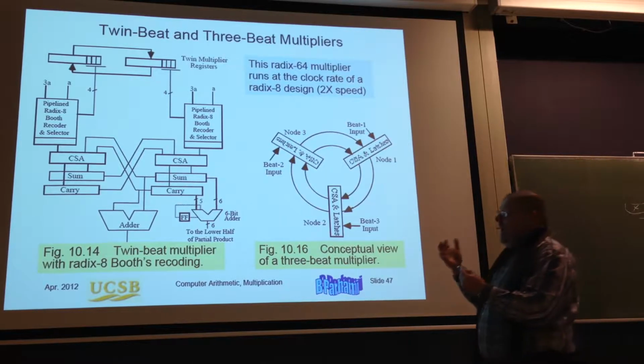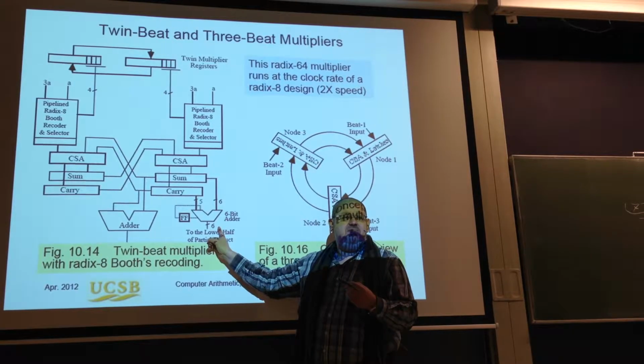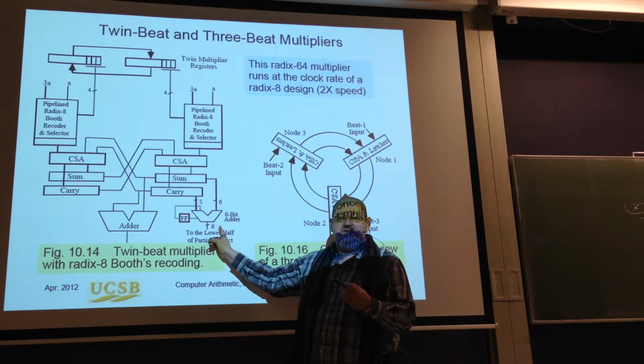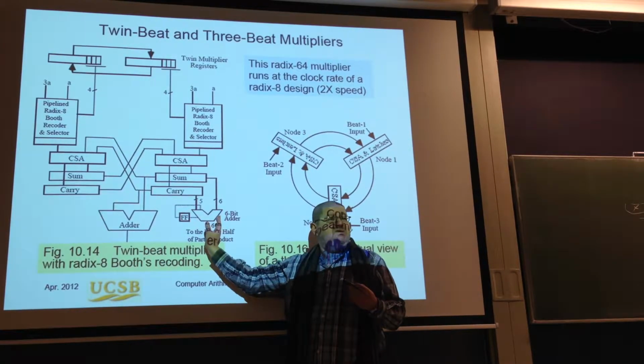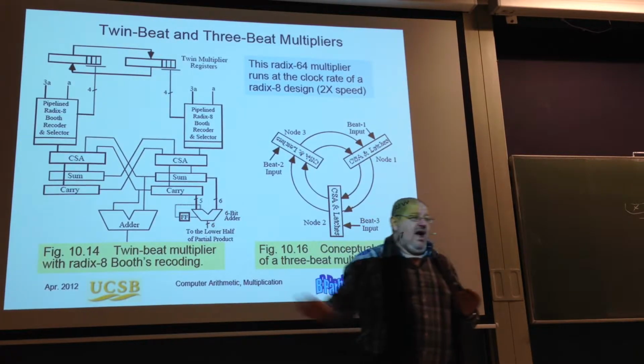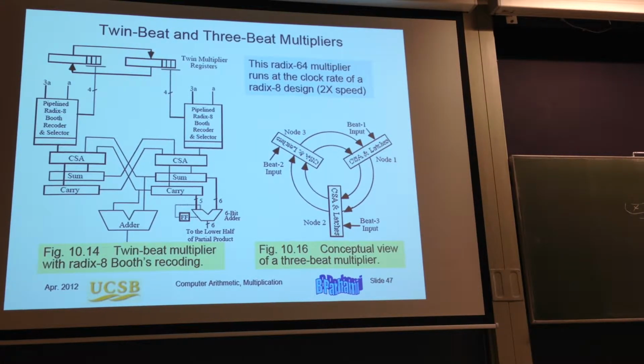I'm reporting for output 6 bits at a time, but they are coming from different sources. At the end of each cycle, I'm ready with these. Then I am working with my nominal frequency, but one of the multipliers is working on the rising edge, and the other one is working on the falling edge.